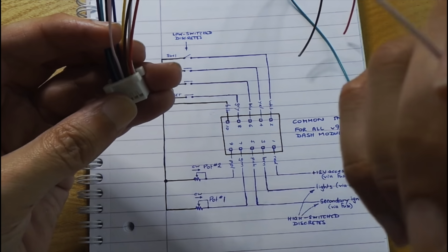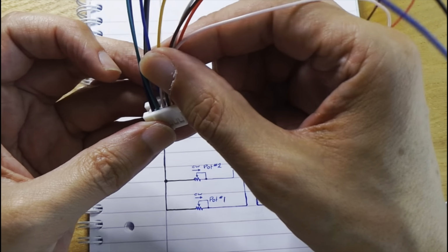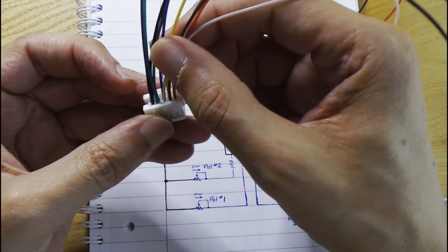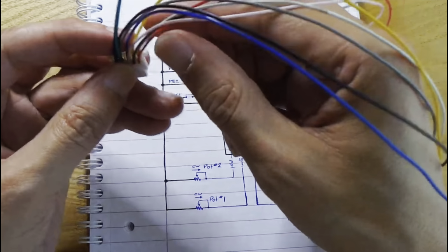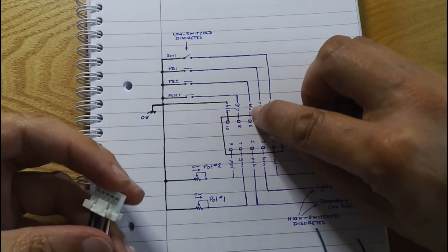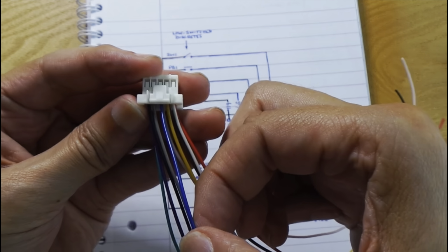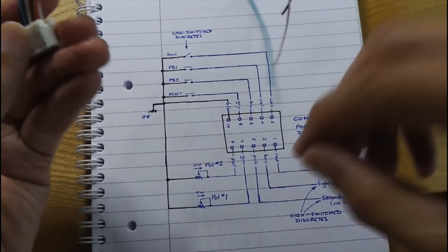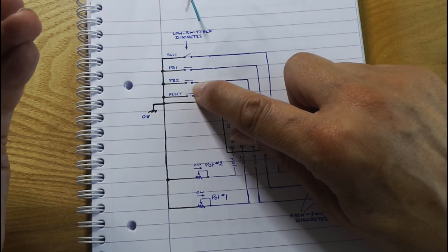So you don't have to connect that one, but it's useful, especially if you're using the dash module number 3 in its fully functional mode, where all of the side indicators and the dash top indicators have real functions. Pin 6 is going to be a blue wire, and that is this one right here, the middle one on the top row, and that is another ground switched input, this time to push button number 2. We'll talk about what these push buttons and the switches enable you to do later in the video.